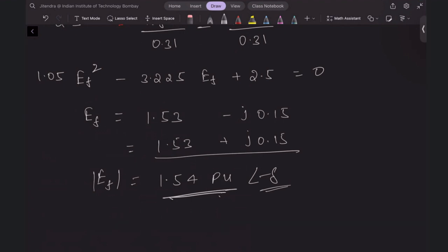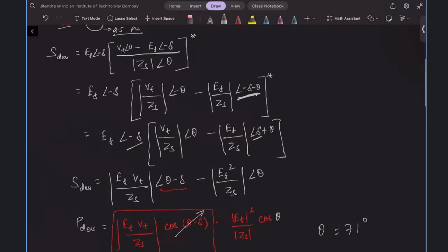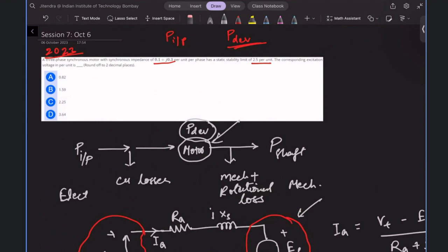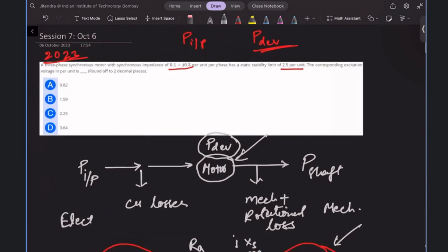Okay, sir. We are using all per unit values here. All per unit values, because the question's data were provided in per unit values. So it's better if you deal in the same terms. And anyway, here no ratings are given, so you cannot convert into actual values. So you have to go ahead with only per unit. There is no alternative in this particular problem.